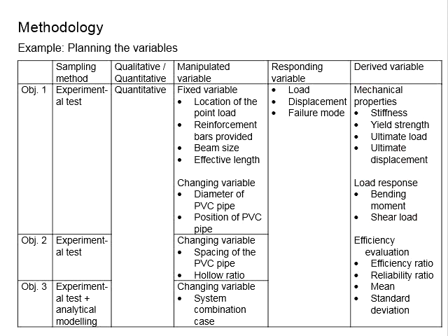Also, you might want to look into the efficiency evaluations based on the ultimate loads that you have acquired with respect to the design of the specimen, for example, the hollow ratio. Then you are able to determine the efficiency ratios of the specimen: how efficient is the material used within the specimens in resisting per unit load acting onto the specimen.